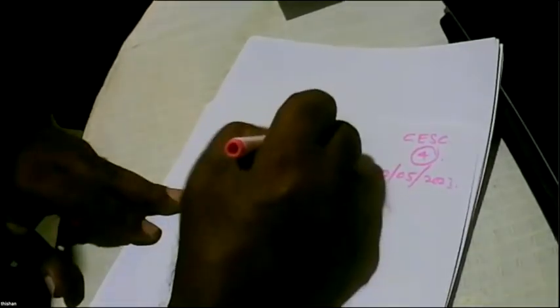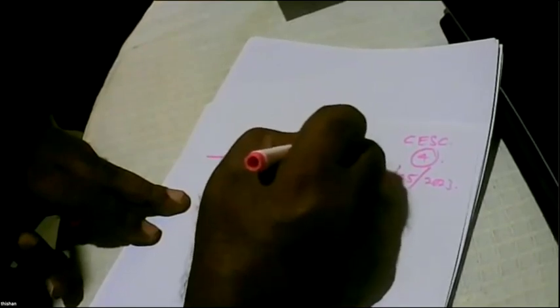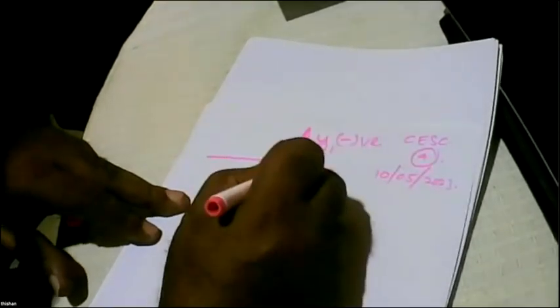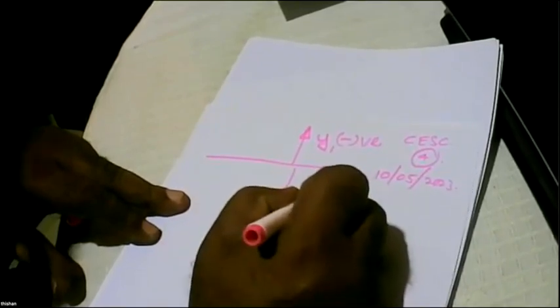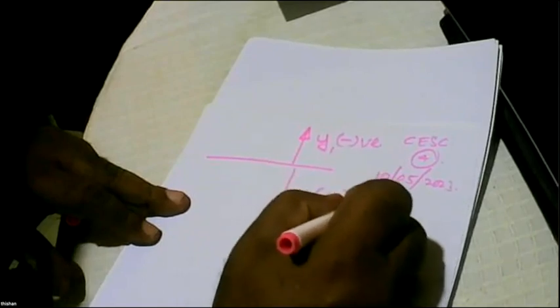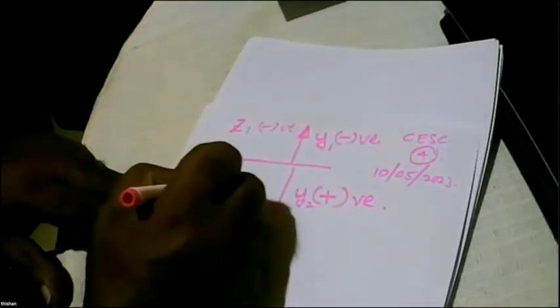Because we have already derived the set of equations, actually we derived it for the simply supported case, then we derived the same thing for composite action. Now today we are going to use the same set of equations for continuous construction. So what are the special conditions in our sign convention? We measure y1 upwards and it's negative. We measure y2 downwards, positive. Z1 negative. Z2 positive.